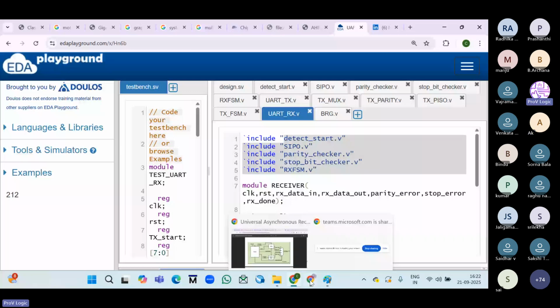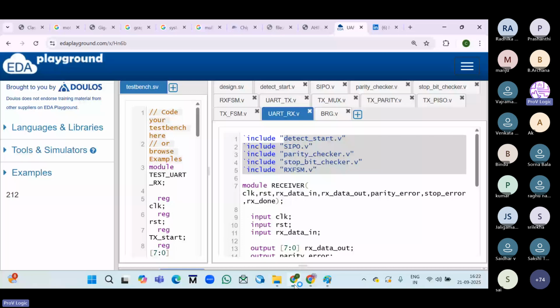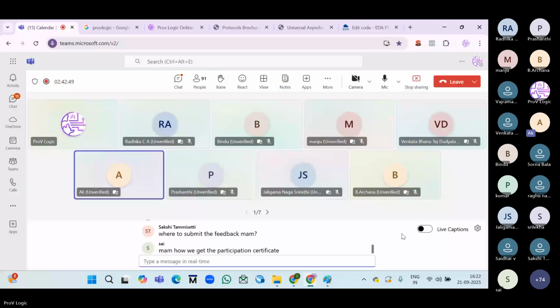For this we write the test bench. In UART we have a Verilog test bench and a UVM test bench also. If you want to learn UVM in more depth, we will share that also. Awesome. The other question was regarding the RISC-V project you had mentioned. What kind of RISC-V project is it? We have a 16-bit pipeline, a 5-stage pipeline, and a 32-bit non-pipeline also. Both.